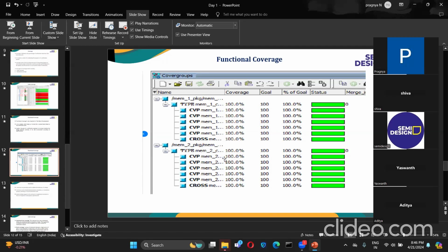Likewise, that also depends on the width of the variable. If the width of the variable is only 2 bits, meaning 1 down to 0, it has a possibility of 0 and 1. So in that, if only one case is hitting, it will give us 50% coverage. Likewise, it will calculate and give the percentage. That will be entirely taken care of by the tool, so we need not think about that, but for information, for having knowledge, I'm just telling you.